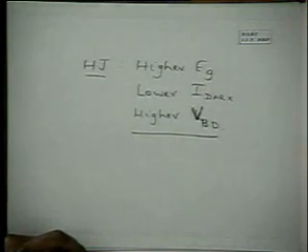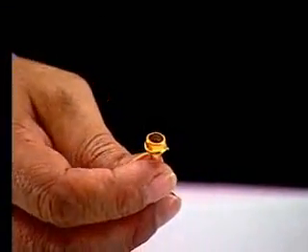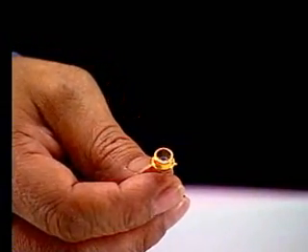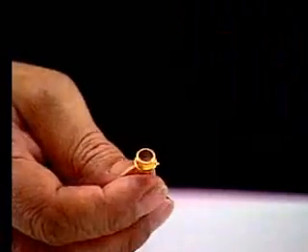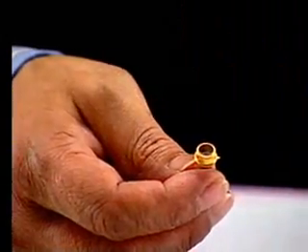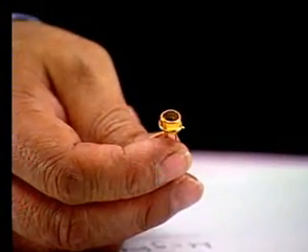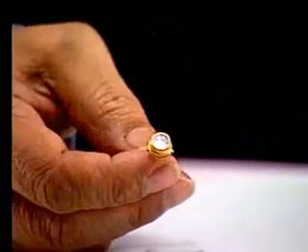I just want to show you a simple silicon PIN diode, and this is a fairly large area silicon PIN diode, which, as you see, has a metallic annular electrode. That is to reduce the surface leakage and the dark current around the junction, and it has an anti-reflection coating. That's why it looks black, dark, and it has one ground terminal, and the central portion is the active area. It's a planar structure with the other contact taken from the bottom of the device. This is a fairly large area device. You can see the diameter is of the order of 2 to 3 millimeters.